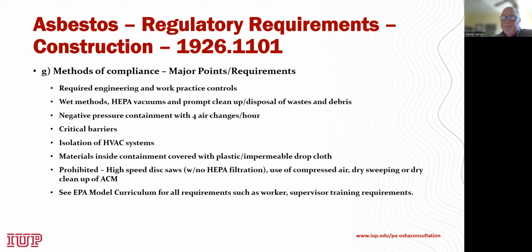There are some tasks that are actually prohibited by the standard: the use of high-speed disc saws with no HEPA filtration, use of compressed air, and dry sweeping or dry cleanup of ACM are all prohibited. And again, there's EPA. If you really want to get into the nitty-gritty details of everything, it can be found under the EPA model curriculum. That lists all the requirements for workers, supervisors, inspectors, everything.